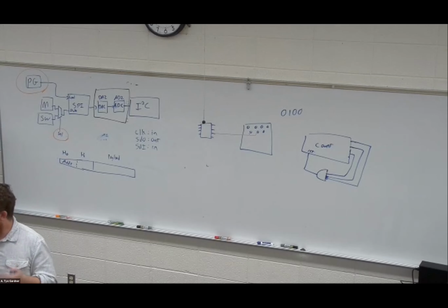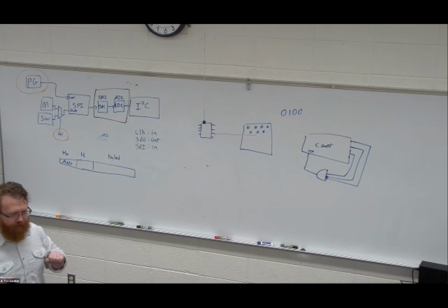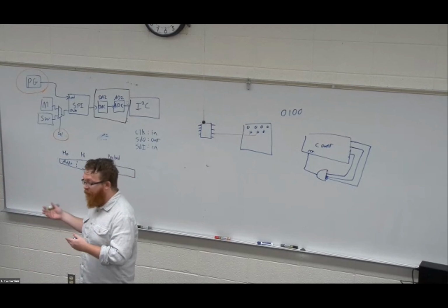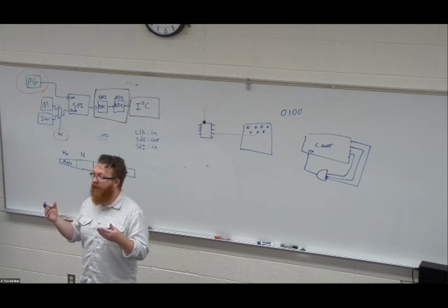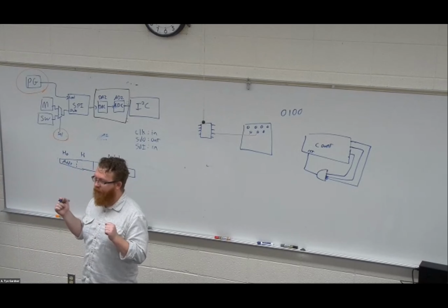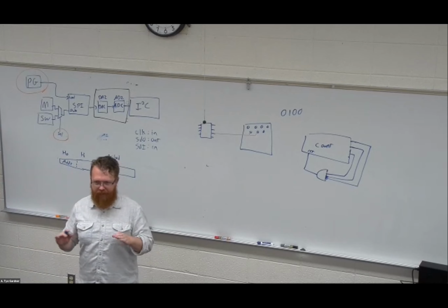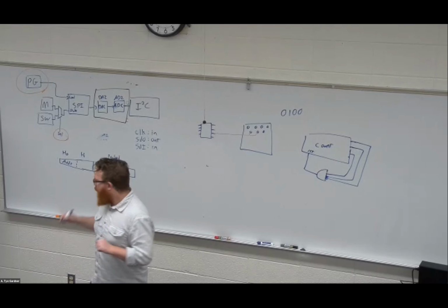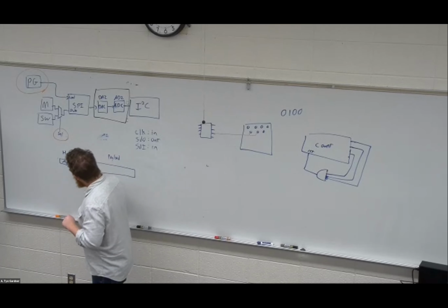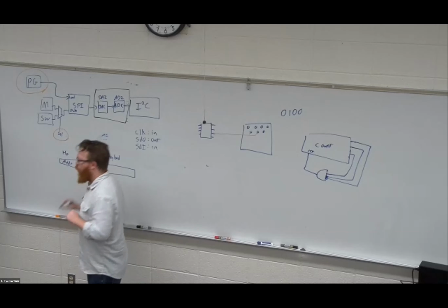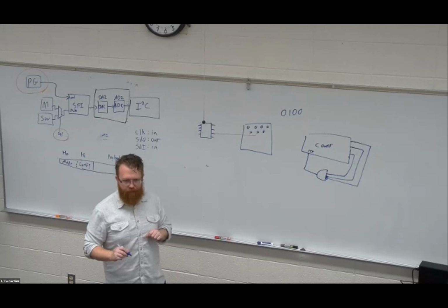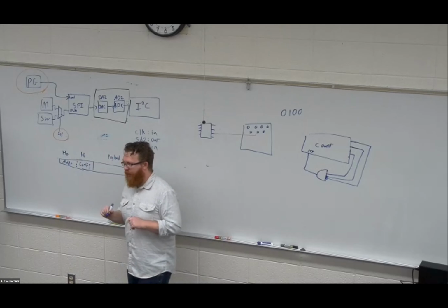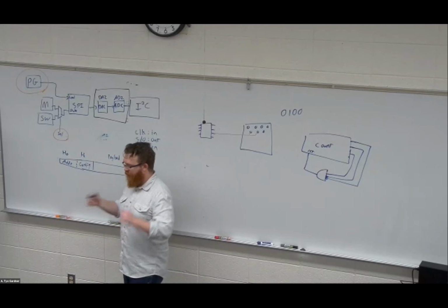In this case, the header contains more information. And I'm going to call it H0 and H1 and kind of split it into two parts, where the first part is the address. And each of these devices have an address affiliated with them. So when they say that number, they're going to have a shift register like we talked about that's going to shift these bits one at a time. And at the end of however many bit address they have, it's going to check and say, is this my address? If it's not, they stop listening. They stop caring about the rest of the payload.